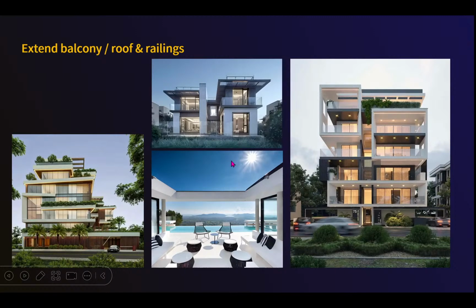Okay. And also, just now we've talked about the extended balcony. Yeah, we can use either the external area drawing on the upper level, or you can definitely draw a room and then put the elements, for example, set the customized height of the outside wall as the railings.